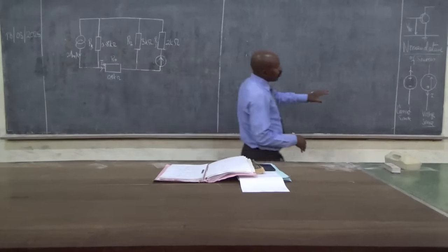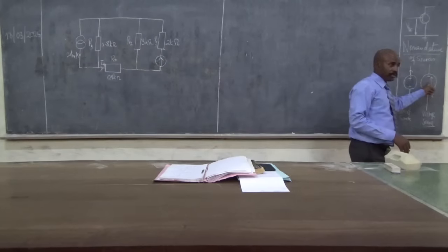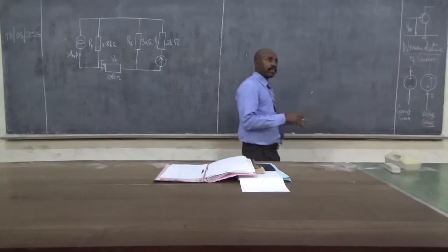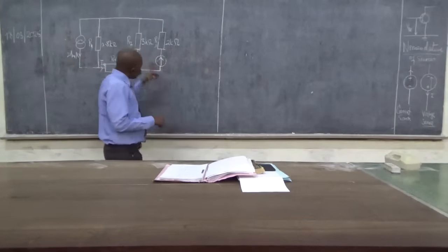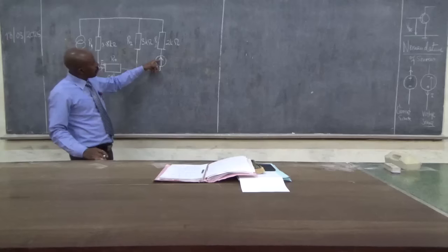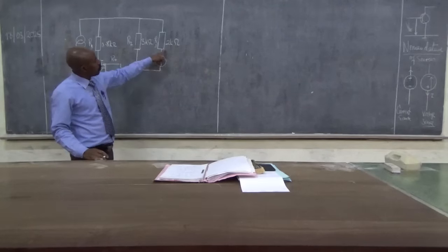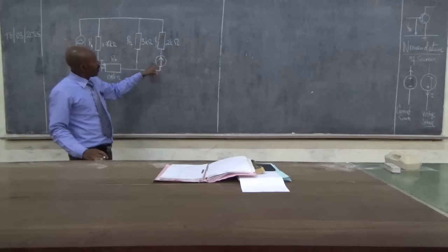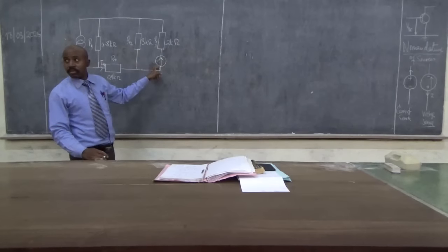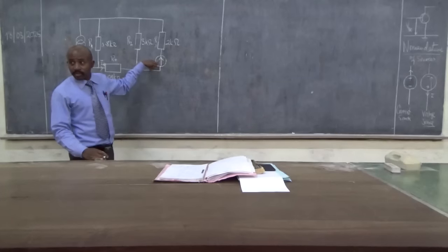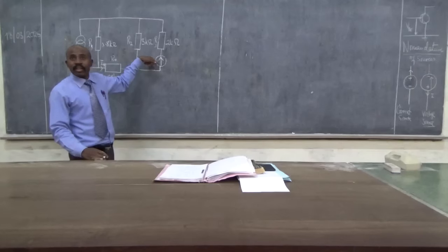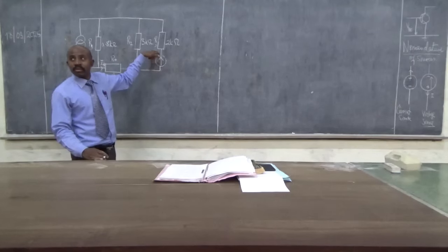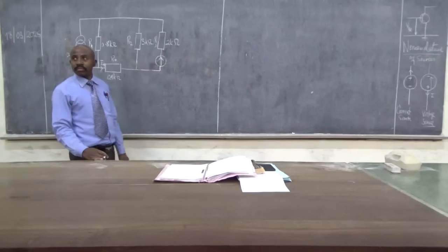I can confirm about some people draw them this way, both of them, but then use the plus and minus to clarify. So to clarify on the case where when we're using superposition, when we had to get the 6 and we were now confused how we end up with 2 milliamperes, the current flowing from the voltage source is from the positive terminal. And when we are drawing the arrow is from high potential to low potential.